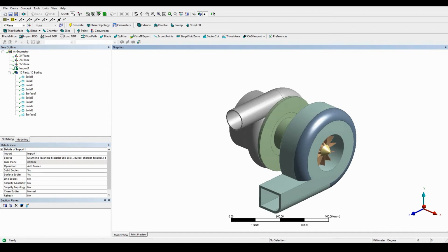And the edges, so to see any issues with the geometry, change the edge coloring. So again here, we can look at the connections depending on what's happening to the edges. So here it's very simple. You've got this tool up here looking at the edges. Click on that, click by connection, and you can see what it's showing you here. So if there's any single edge connection, it means the geometry is open and not a solid body. So here it means that this is not a solid body, and we need to fix this to move on.